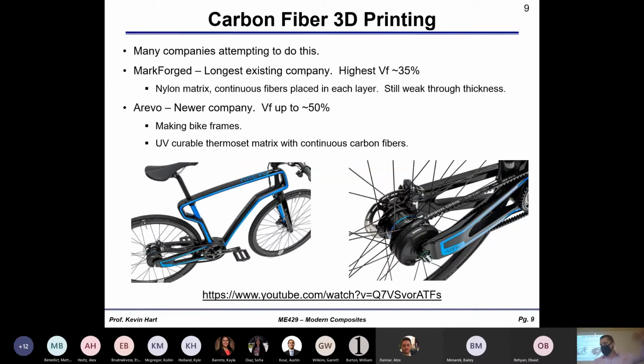All right. Next, carbon fiber 3D printing. 3D printing obviously is like all the rage. You know what I'm saying? For the last 15, 20 years, it's been a pretty powerful and pretty interesting manufacturing method, though it hasn't come to light really in engineering application because the strength of the interlayer is relatively weak. A lot of people have looked towards trying to strengthen the interface by, let's say, 3D printing with carbon fiber and epoxy at the same time.